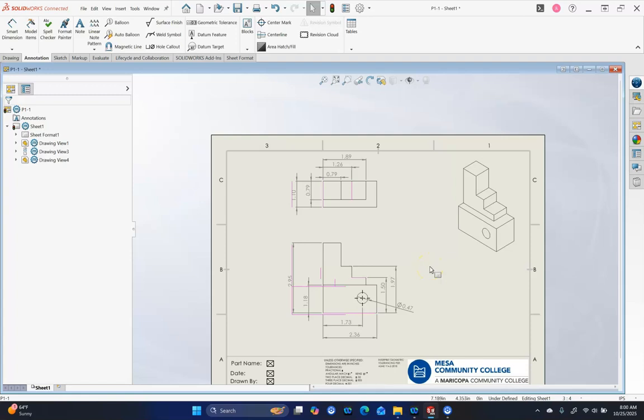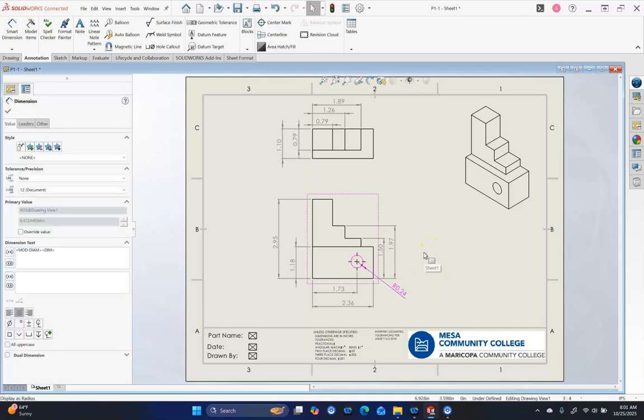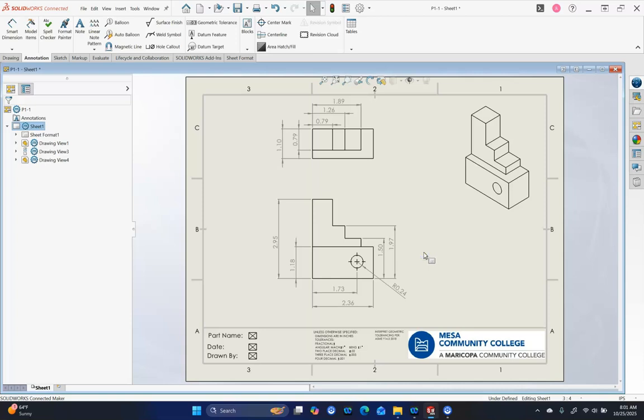All right, so I'm getting ghost images. This happens on the drawing. My video card doesn't resolve those, so a Control Q forces a rebuild, and then that allows the screen to update.